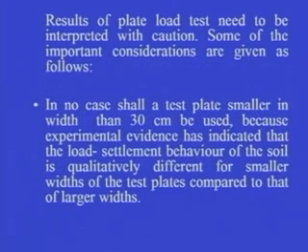Results of plate load test need to be interpreted with caution. Some of the important considerations are given as follows. In no case shall a test plate smaller in width than 30 centimeter be used, because experimental evidence has indicated that the load settlement behavior of the soil is qualitatively different for smaller widths of the test plate compared to that of larger widths.